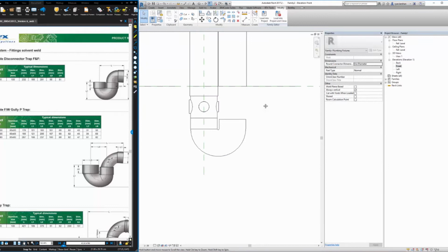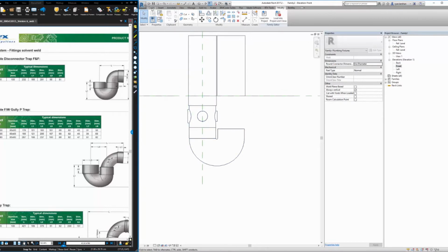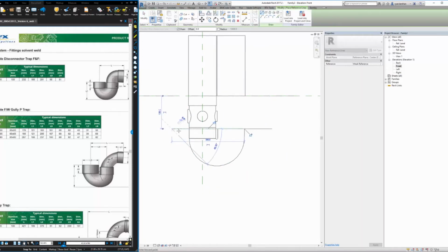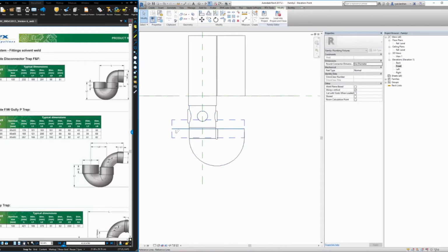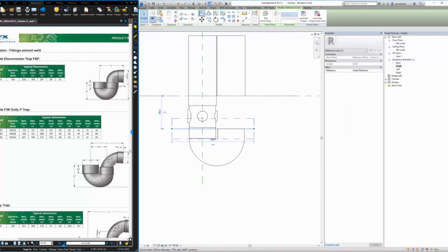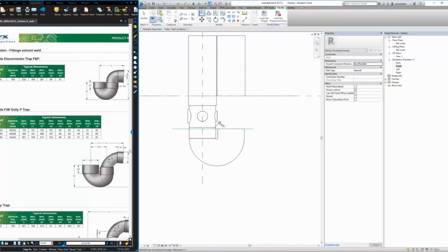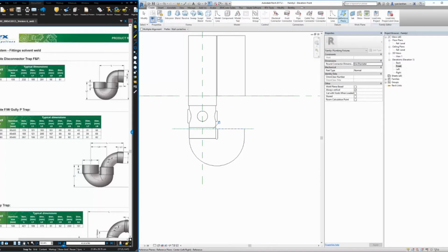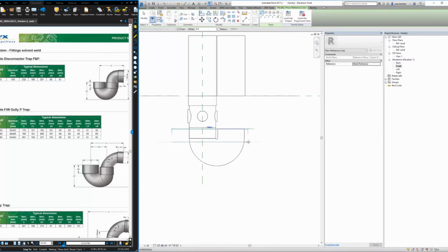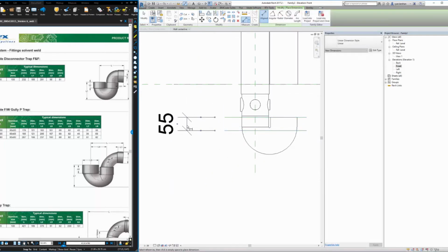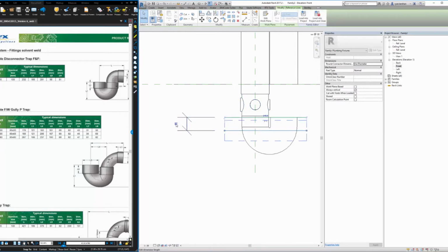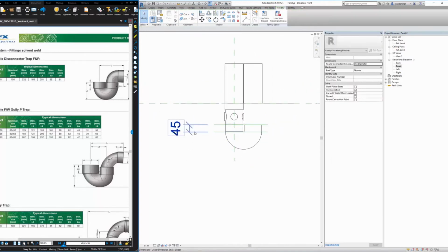And you can see there we got two weird extrusions out the top of our reference plane, our level reference plane. So I'm popping in a reference line here. That's going to be the top of our socket. And I'll just align and lock that to the top of our bend. And then again, we've got the depth of our socket, which we want to be fixed. And we're going to fix that in at 45. So now we align and lock our extrusions there to our reference lines.